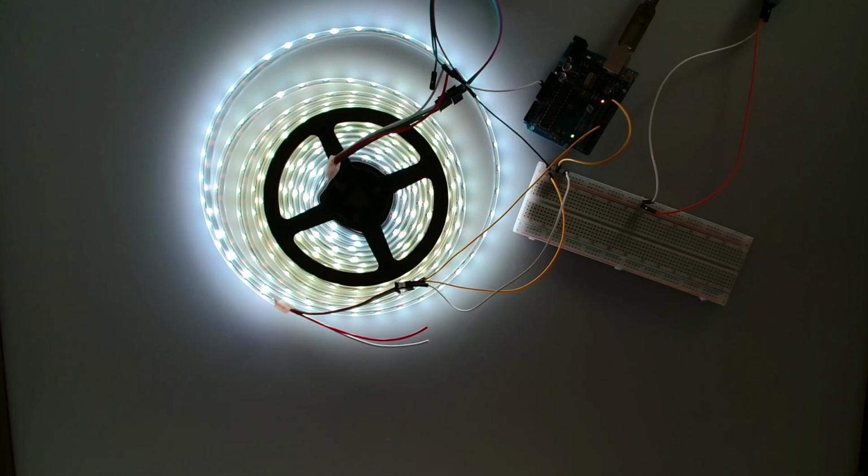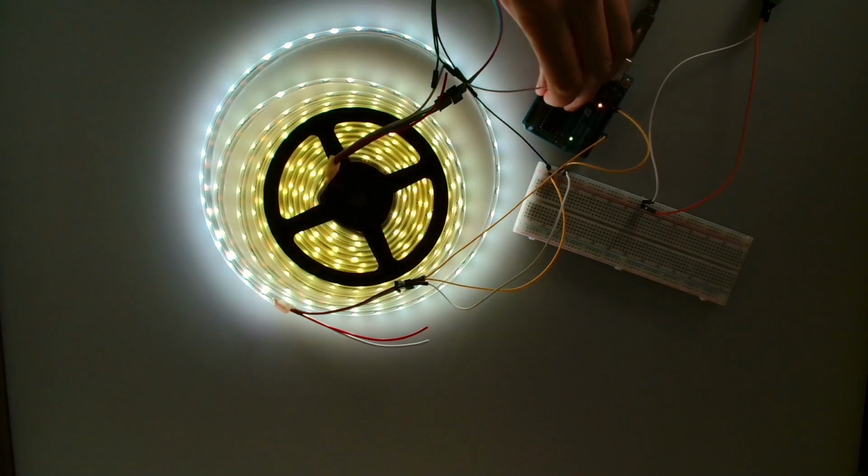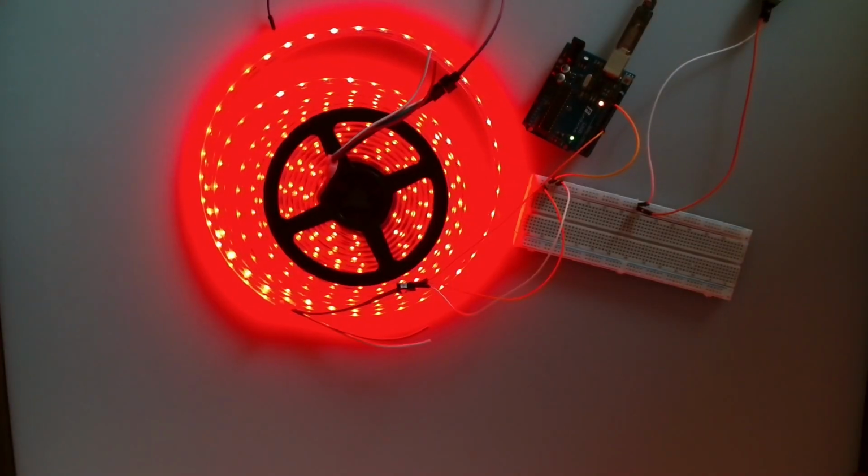You see this most with white. If you're doing any other colour, it's less overall power, because you're powering fewer overall channels. You basically have less of an issue with voltage drop. This primarily applies to white. If you were to convert all of these to red, you wouldn't have this same problem. In fact, if I unplug this end, Ethan, can you put them all to red, please? You can see we have no real issue with voltage drop, because we've gone from 150, 150, 150 to 255, 0, 0. So, something to be aware of if you're using white lights.